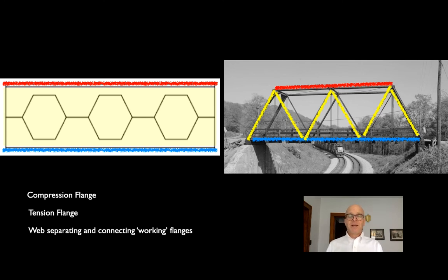We can also, of course, as we did before, zoom out and look at the truss as a series of points or nodes that are held in equilibrium by each of the chords, right? There are multiple ways that we can calculate or interpret a truss. It ends up working a little bit like a beam in this sense, and like a really, really efficient beam, in that the web is replaced by these almost nothing struts, compression and tension struts, that literally hold the two flanges, or in technical terms, the top and bottom chords, in place with one another. And we'll see that again and again.